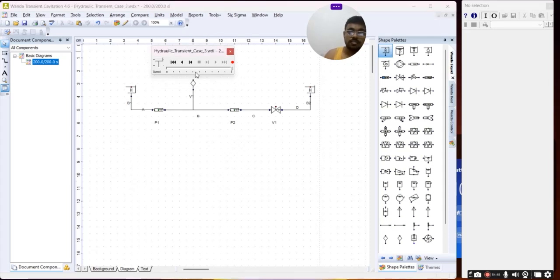And there are a lot of chemical industries where the chemicals are being carried by pipes, right? So those pipes have to be designed keeping this hydraulic transient in mind, so that, due to pressurization, very high stress concentration is not developed at the crack tips within the pipes, those cracks that are present in the pipe.